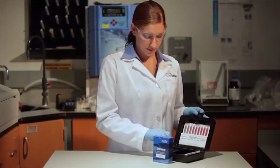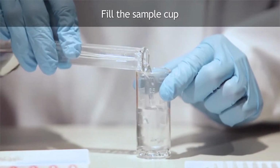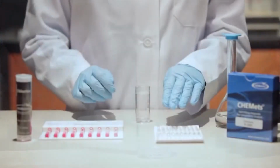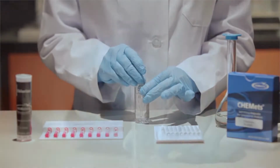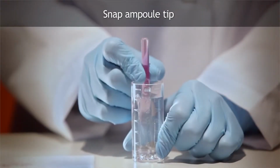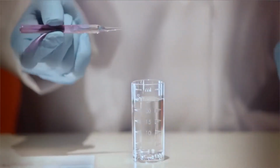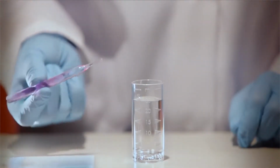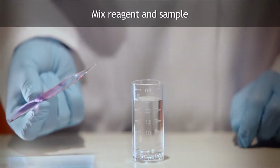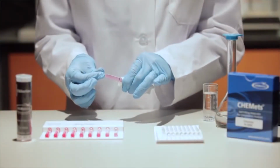To perform a test using the Chemet's test procedure, fill the sample cup to the 25 milliliter mark with the sample to be tested. Insert the tapered tip of the ampule into one of the depressions in the bottom of the sample cup. Snap the tip of the ampule by pressing the body of the ampule against the side of the cup. The vacuum in the ampule quickly pulls in the correct volume of sample. Mix the contents of the ampule by inverting it several times, allowing the bubble to travel from end to end.